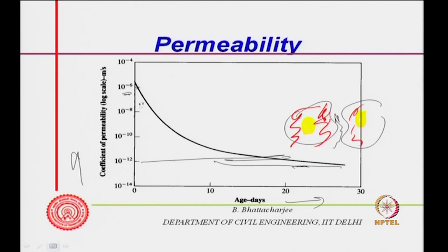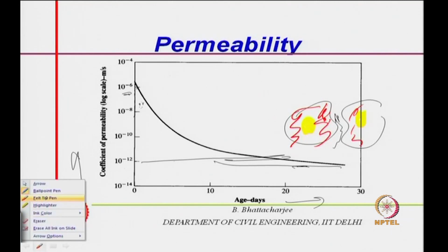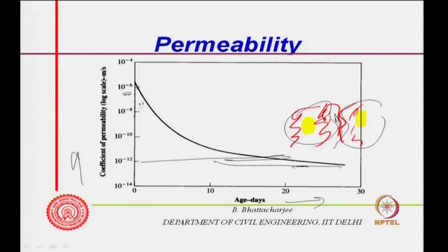As the hydration progresses, the hydrated cement will reach there, capillaries will get segmented, and we talked of capillary segmentation earlier. Therefore, interconnectivity will get reduced. With more hydration, first the total capillary porosity will reduce and segmentation will increase, so they will be less interconnected.